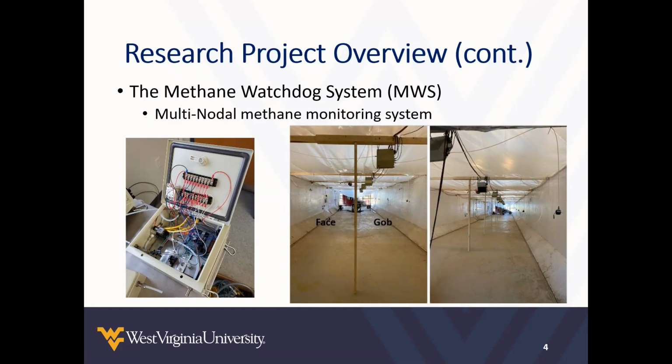But in principle, could you measure some other substances? Can you measure propane in the same manner? I'm sure that you could. We have this block here, and you could probably put an ethane or a propane sensor in there if you wanted to. I know there could be small traces of ethane in longwall mining, so that's something to think about. But I'm sure you could sample it the same way and just add an additional sensor into the block here.